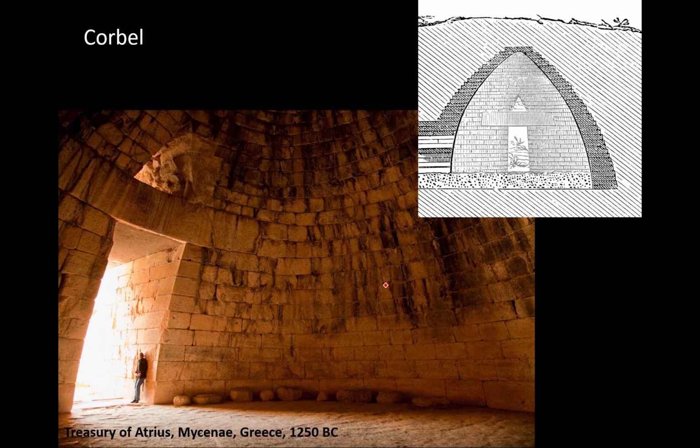This is a corbelled dome, so it's basically doing that idea, but three-dimensionally in a circle. It's a round-shaped room, kind of like a cone, and each stone is offset slightly inward and corbelled. You can see that this one goes like that, and the next one goes like that, and like that, and then they came and shaped each one in a smooth round shape.